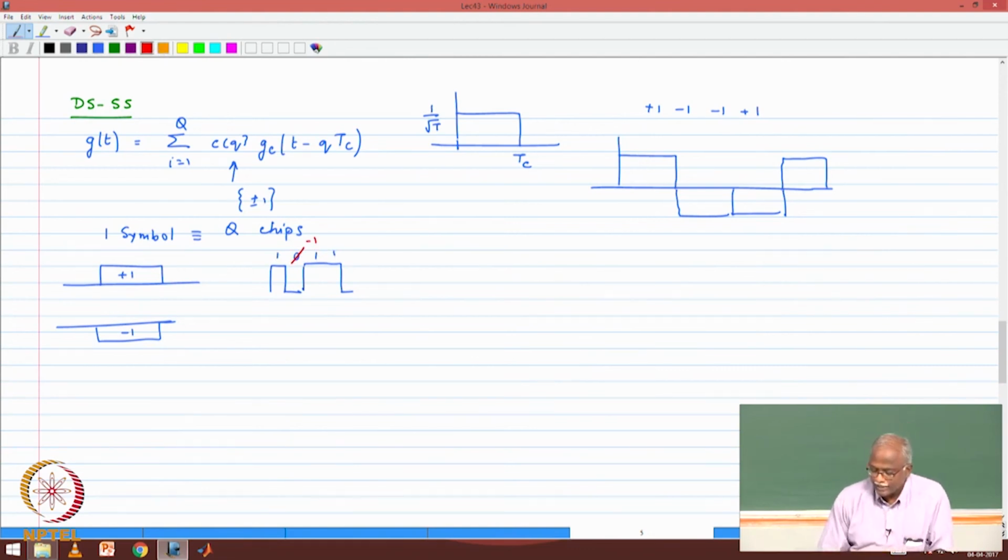So if I want to send the waveform of the other polarity, basically it will be a flipped version. So again, the basic operation of spreading, I'm assuming you're familiar with. Now, very often in the context of spread spectrum systems, I just want to say that at the beginning itself, we are talking about a waveform that is binary. For example, the Walsh-Hadamard code, the spreading code. We'll talk about it in terms of ones and zeros.